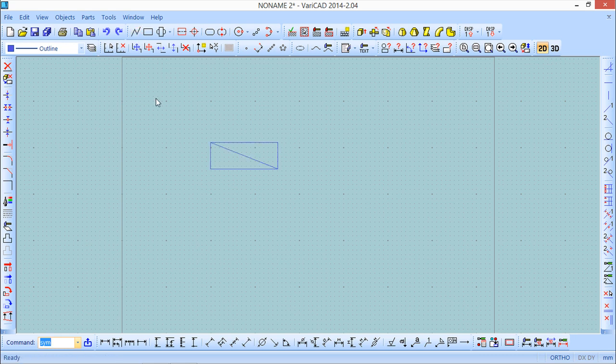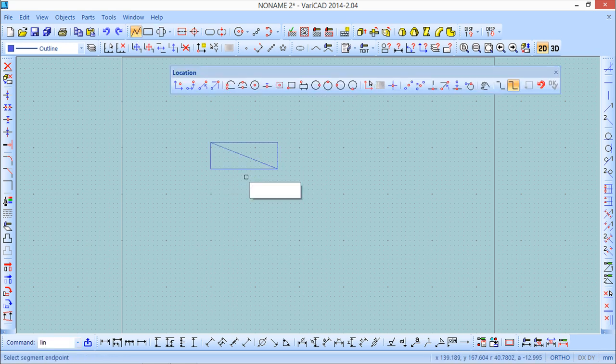You see that when I cross over the object, the complete object is grouped in one set. It's a symbol, but it's grouped, so it is recognized as just one entity. So, for example, if I want to create a line and I try to grab objects here, you see that normally I should grab the endpoints here, but they are not recognized; what is recognized are the insertion point and the connection point. So these are the purpose of these two objects.